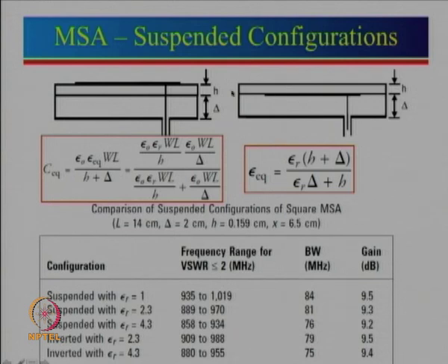So now comes the next part: how do we support these antennas? And if this has a good thing, then why use this one here? First of all, the major problem with this is, let us say we put a ground plane here and we have put an antenna there, and we need to solder here. Sometimes it becomes very difficult; I have to bring the solder either from the side here and all that.